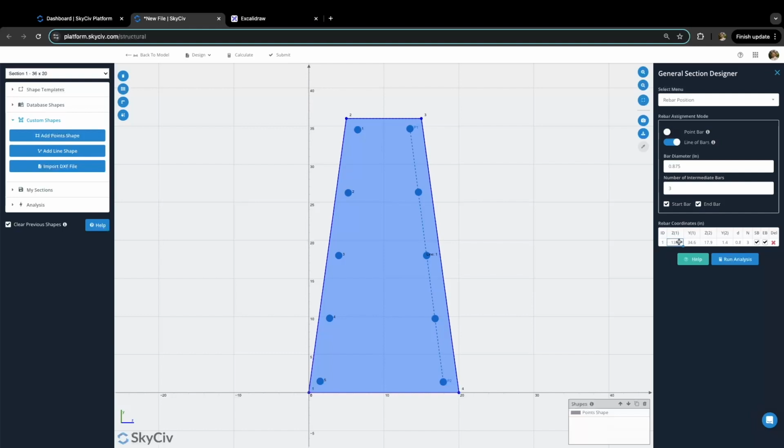And then basically we can modify the coordinates. So Z1, Y1 is the coordinates of this point, and Z2, Y2 is the coordinates of the second point. So we might slightly tweak those to reflect the other side as well. So we'll go 34.5 here. Leave that as 13.5 there. And then 18.5 and 1.5. And yeah, we've got pretty much just line of symmetry there now.